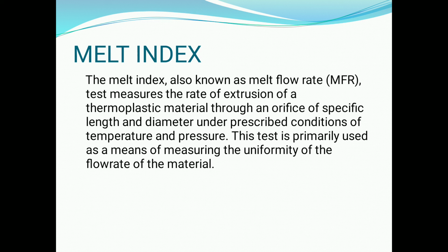The first test of plastic is melt index. The melt index is also known as melt flow rate, that is MFR. This test is used to measure the rate of extrusion of a thermoplastic material through an orifice of specific length and diameter under prescribed conditions of temperature and pressure. This test is primarily used as a means of measuring the uniformity of the flow rate of a material.